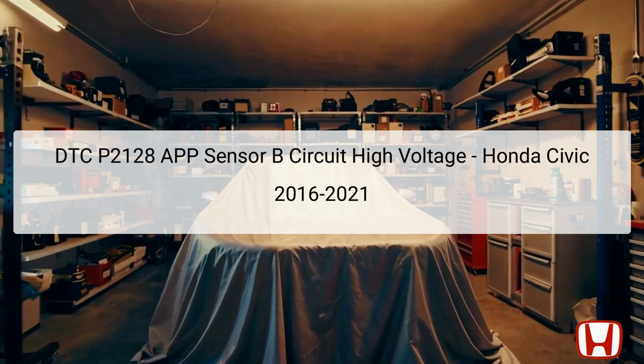Located within the vehicle's accelerator pedal assembly, the APP sensors play a crucial role in relaying accelerator position information to the Powertrain Control Module, PCM. This data is vital for engine management, dictating how the engine responds to driver input. Therefore, diagnosing and addressing a P2128 code is essential for maintaining vehicle performance and safety. It's recommended to follow the specific troubleshooting steps outlined to ensure an accurate diagnosis and effective repairs.